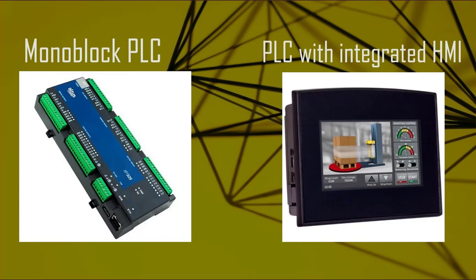Overall, the choice between modular and monoblock PLCs will depend on the specific requirements of the application and factors such as cost, space constraints, and the need for future expansion or modification.